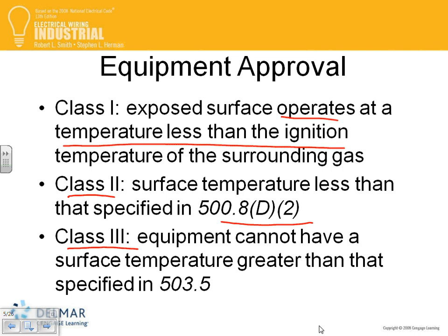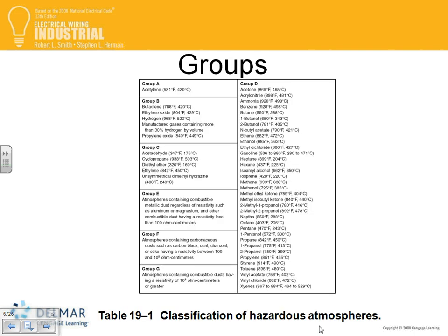Here's a group, if anybody's interested in group A, what type of location? Read through them. There's a lot of gases, names of gases, guys. Groups A, B, C, and D. I believe these were class 1, and these three, F, G, and H, were class 2. We classify them based on 310. Yep, class 2.